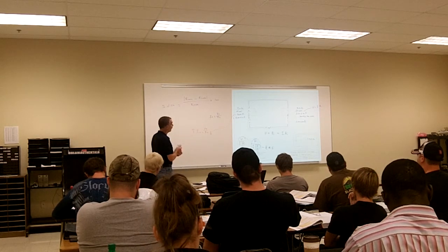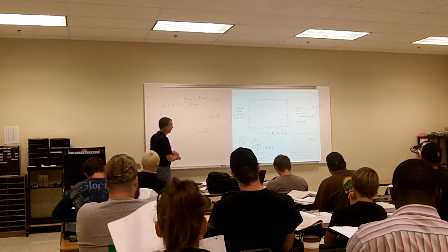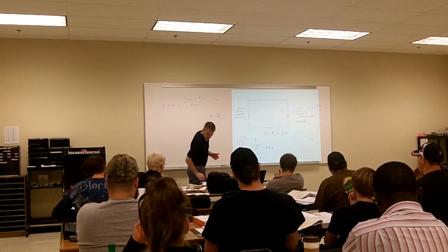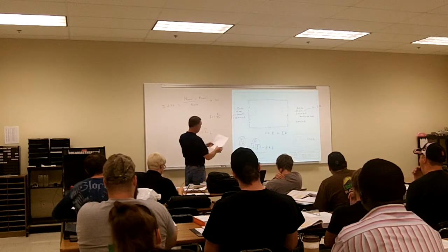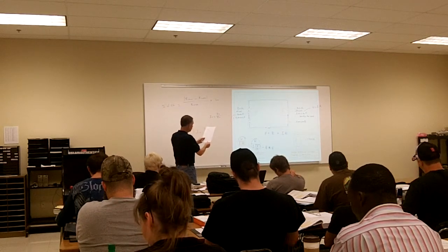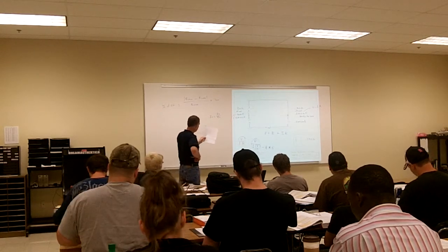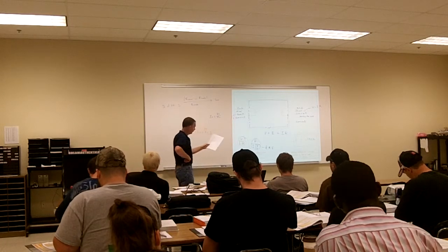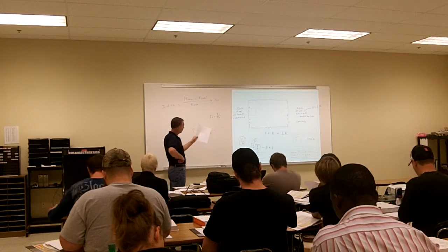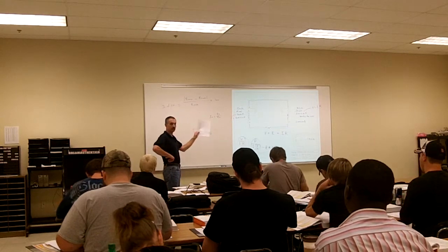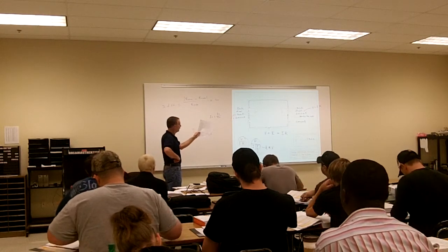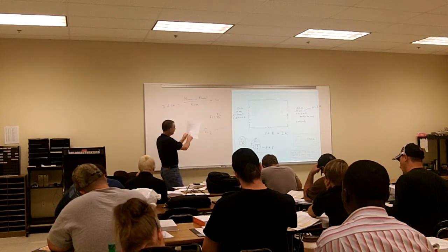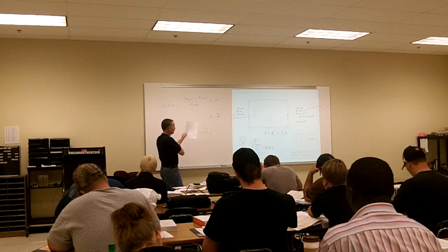All right, so then what we do is a lot of troubleshooting. Now remember, a lot of our troubleshooting is done with a voltmeter. So on our study guide, under troubleshooting, we need to know a couple of things. Measuring voltage across an open: when you're measuring voltage across an open, you're going to see your source voltage. So under your troubleshooting guide, where it says measuring voltage across an open, you'll see your source voltage.